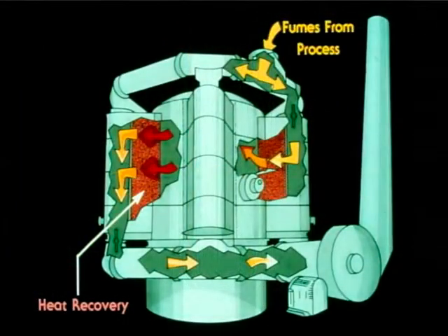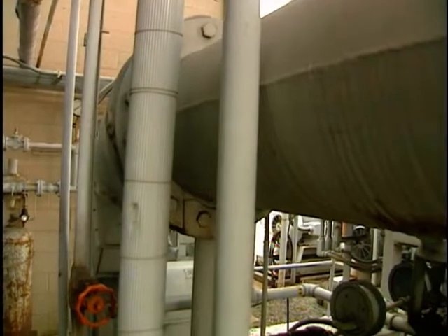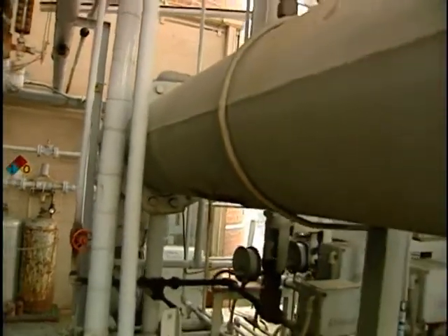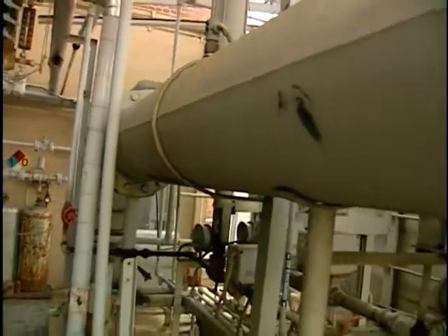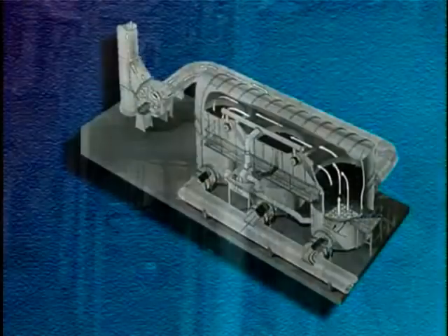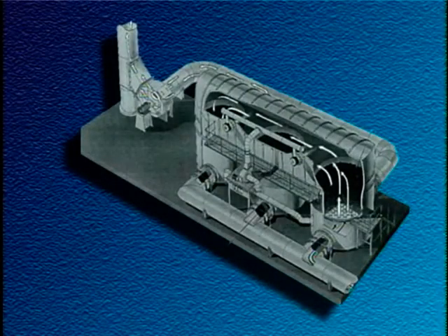A regenerator is a set of refractory beds that store heat. Heat recovery is achieved by passing the waste gas stream through a packed ceramic bed at the inlet to the incinerator that was previously heated, with the gases exiting the incinerator. It is common to use at least 3 beds in a regenerative system.